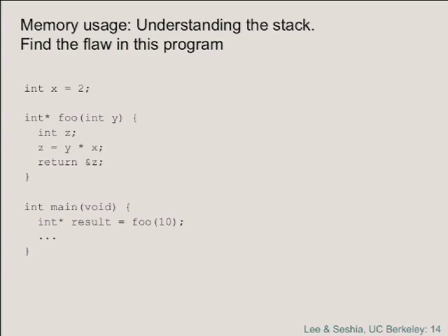Yeah, if you're multi-threading, definitely not. But multi-threading is an operating system level concept. We don't have an operating system here. This is bare iron. Sorry? What if an interrupt occurs? Okay, interrupt is a bare iron concept. By the way, it's how multi-threading gets implemented. So interrupt is a more primitive concept.